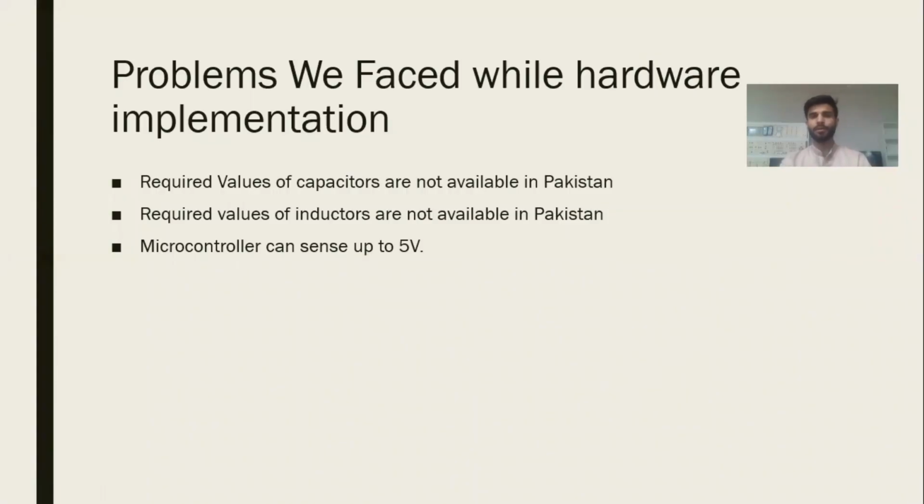So coming toward the problems we faced while hardware implementation, we needed capacitors and inductors of values which are not available in our country. So as far as capacitors are concerned, we have combined capacitors in series and parallel to get the desired value of capacitor. In case of inductors, we designed our own inductors using toroid material.